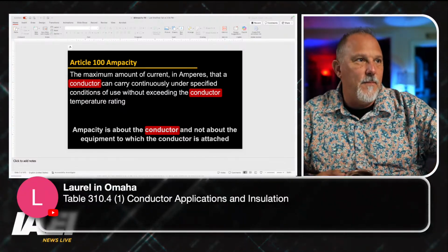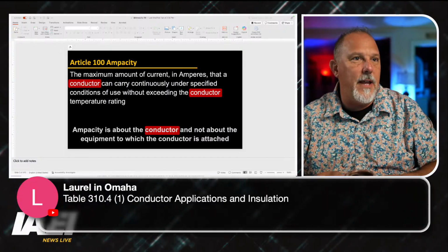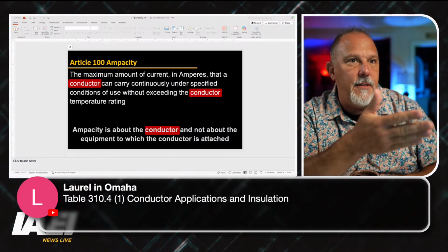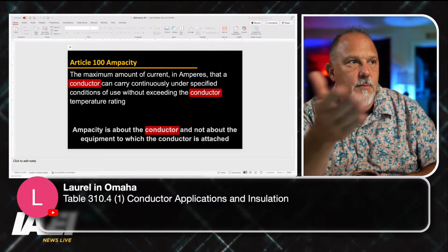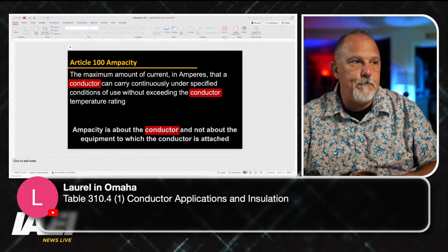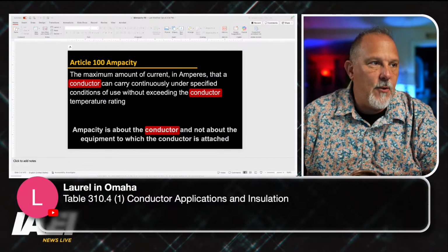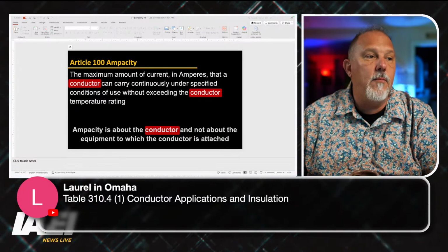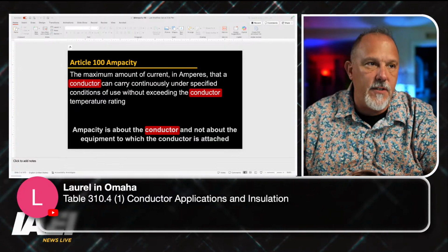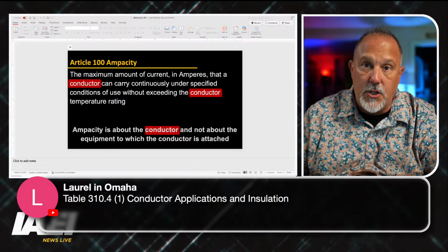So you have tables or engineering supervision, and they point to 310.15 and, under engineering supervision as provided in 310.14(B), where more than one ampacity applies for a given circuit length, the lowest value has to be used.